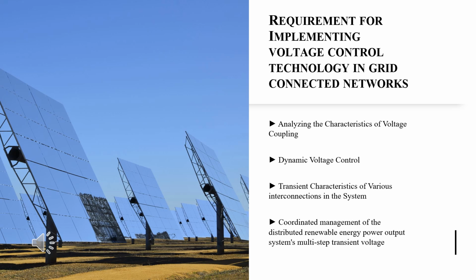The transient properties of distributed renewable energy stations, which include converter stations in both AC and DC systems and reactive power compensation equipment, are examined for integrating renewable energy in the grid. Conventional power system transient stability analysis techniques, including time domain simulation, power flow analysis, and the dynamic safety domain methods, are analyzed, particularly when it comes to grid short circuit problems.